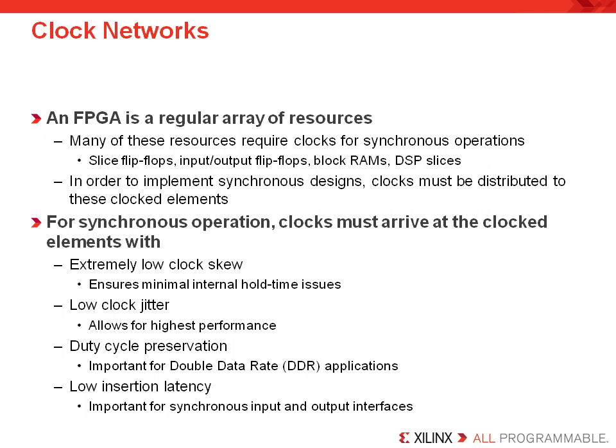Duty cycle preservation is important for double data rate applications, which use both edges of the clock signal. A 50-50 duty cycle is ideal because it gives the rising and falling edge data the same timing characteristics. This minimizes the clock insertion delay and is important for I/O interfaces, since an I/O interface has data signals that travel directly between the external board and the I/O block inside the FPGA.